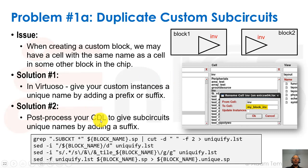Solution number 2, we can post-process our CDL. As I told you before, post-processing is not a great thing to do, but we can do that. We often have to do it, especially if we are not in charge of these IPs and we just get them and there's this type of a thing. Then we can post-process them by adding a suffix or a prefix. And here's a short script that will do this. It will actually go over our entire SPICE netlist, and it will find all the module names and add some sort of a suffix to all of them. So that's another option. There are other options inside the custom flow where when we export our CDL, we can add some sort of a suffix or prefix, but I'm not going to go over that right now.